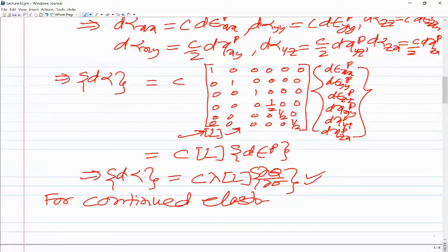Okay sir, and what is the physical significance of alpha? Alpha is, that's what I explained to you, the kinematic hardening in my first lecture, no? Experimentally what is observed is that if you load the material, let's say first in tension, then at some stress level there is a yielding, and after yielding you continue loading up to some point in tension. So now let us say this is the initial yield stress sigma y naught. This is sigma xx and this is epsilon xx.